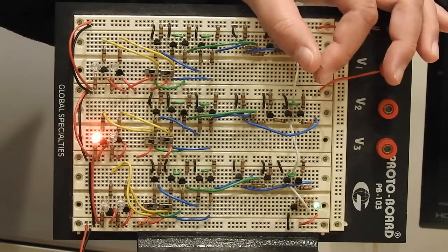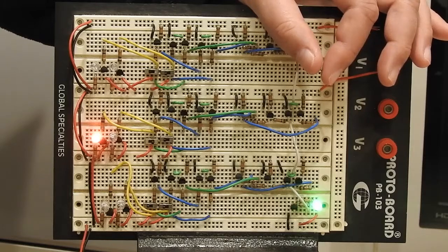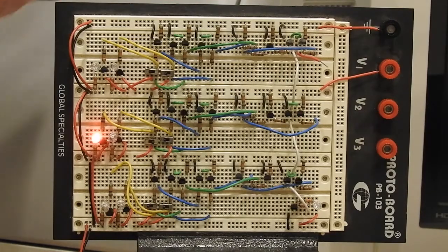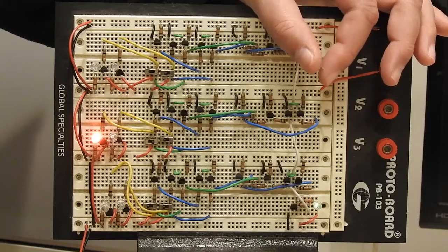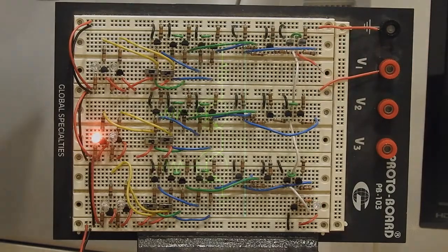The red wire that I'm touching now is also connected to our bus, and notice that when all of our output gates are disabled, none of them are driving the bus wire either high or low. The bus wire is said to be floating, which means it's subject to all sorts of interference, such as the radio signals passing through my body. As I touch the bus wire, the signal LED at the bottom flickers slightly.